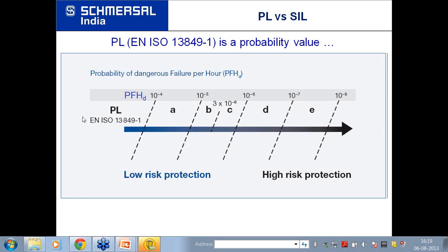In my opinion, both mean the same. Dual check safety, even the safety relay, the job is dual check. If you achieve dual check safety with a device other than a safety relay, there may be a problem, because a safety relay has many other functionalities like internal diagnostic checking capability, which if your device doesn't have, then there may be a problem. Otherwise, both should mean the same.